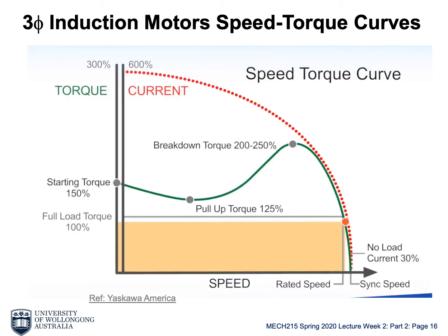When we design a 3-phase induction motor for a certain application, not only should we consider when it's working at steady state, where the torque, power, and speed of the motor need to suit the application, we should also consider the startup process, because the motor needs to speed up to the rated speed.